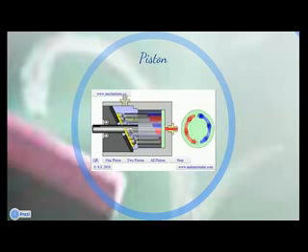For the pump, the piston moves toward the green port plate when the cylinder color is red, and away from the port plate when the cylinder color is blue, and the opposite is true for the motor. This is also shown on the port plate disc on the right. The red circles ride on the red crescent, and the blue circles ride on the blue crescent. The opposite is never true.